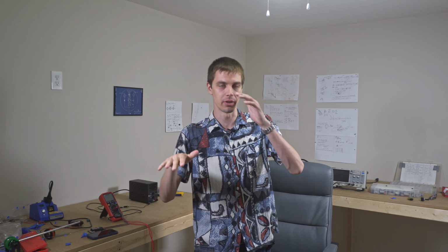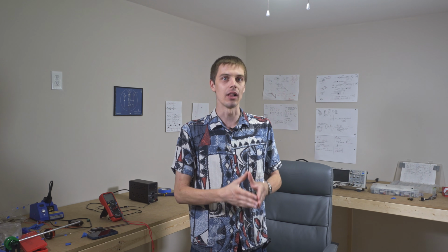In my mind, this is a perfect analog because capacitance, the amount of water that you have to flow into the wire to change its voltage, matters when you're trying to change the voltage of the wire. But in DC, once the whole thing reaches steady state, it just doesn't matter, which is why this particular model works really well for things like Ohm's law, where we're looking at steady state, how the voltages settle out after a long period of time.